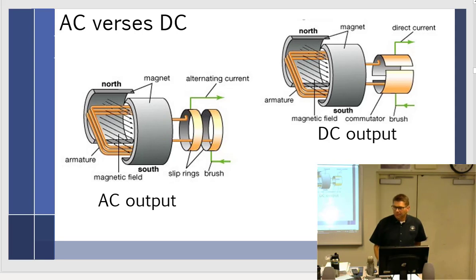There are two of them because you've got, we can say, a positive and a negative. The positive one comes in, goes through the windings of the field and back out. So all you need is little tiny brushes, because the only thing flowing through those brushes in the slip ring on an alternator is what? The field current. Just a couple amps. So you have a 100 amp alternator. How much current is flowing through the brushes? 2 or 3, just a couple amps. So where then is all of the current that's being generated going out of?